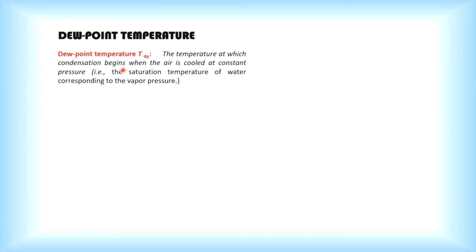The temperature at which this dew is formed is called the dew point temperature, the temperature at which condensation begins. As the cold saturated air touches the cold can, the moisture in the air is squeezed out of the bulk of the air and left behind on the surface of the can as dew, or droplets of water, which we sometimes call condensate.